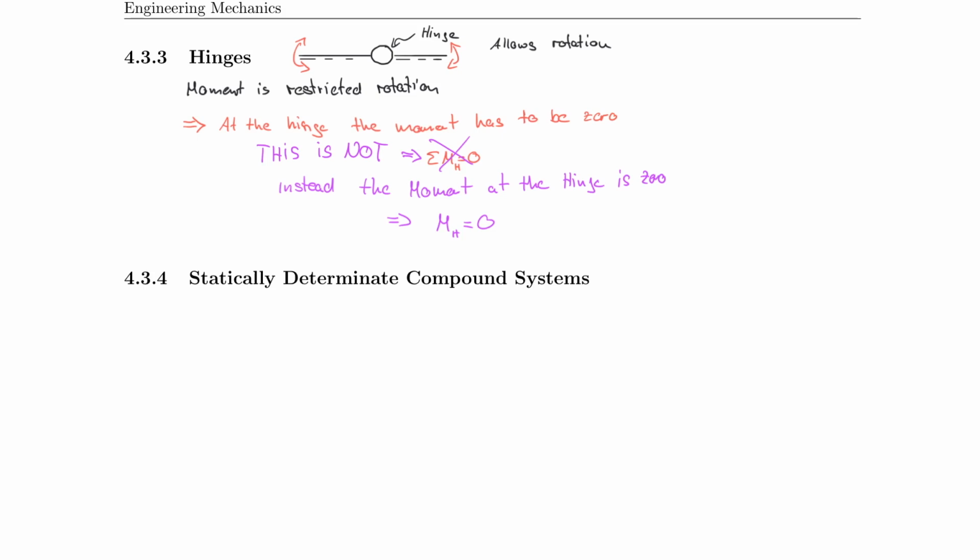So here's why that works. So the way it looked was something like that. And it really doesn't matter what the angle is or what the dimensions are. Conceptually speaking, the reason this system works is because, yeah, you have 1, 2, 3, 4 support reactions, but you also have another initial condition, which is the moment being equal to 0.